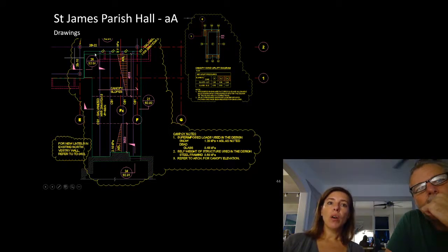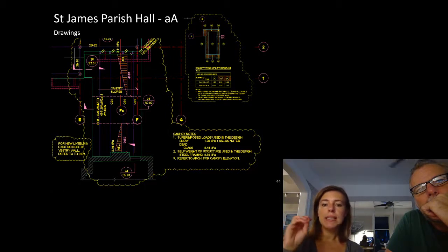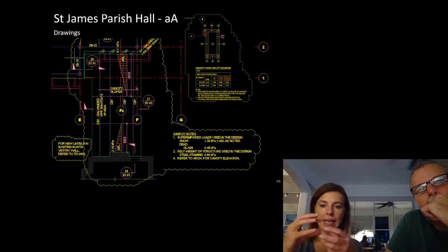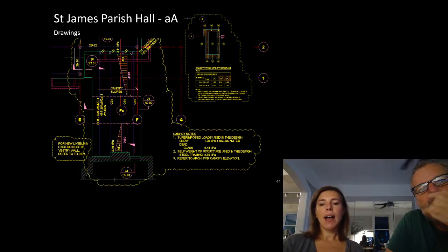We needed all our work to really be happening with these steel columns, but the architect had the requirement that they wanted to see none of the connections. They wanted it to be perfectly hidden. But that means we needed all of the work to be happening inside the HSS. But this needed to be moment connections, kind of complex moment connections.